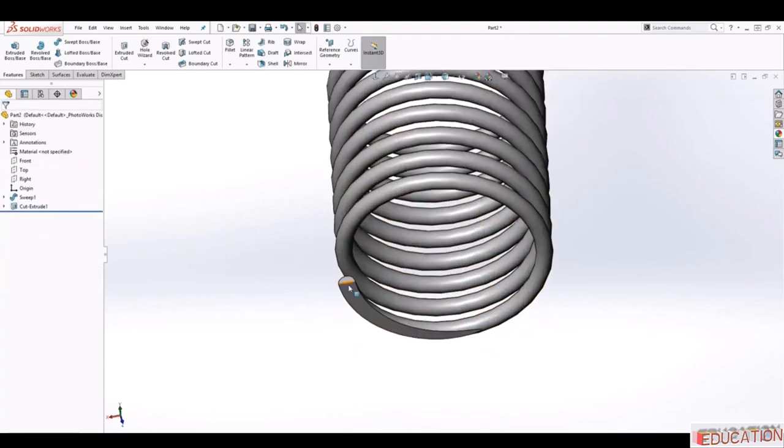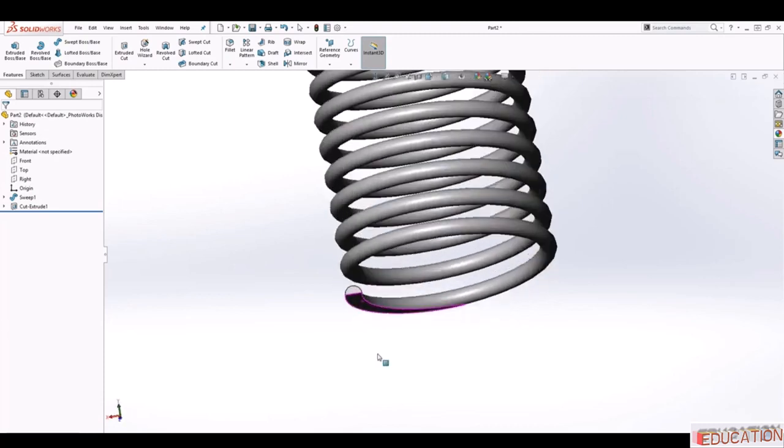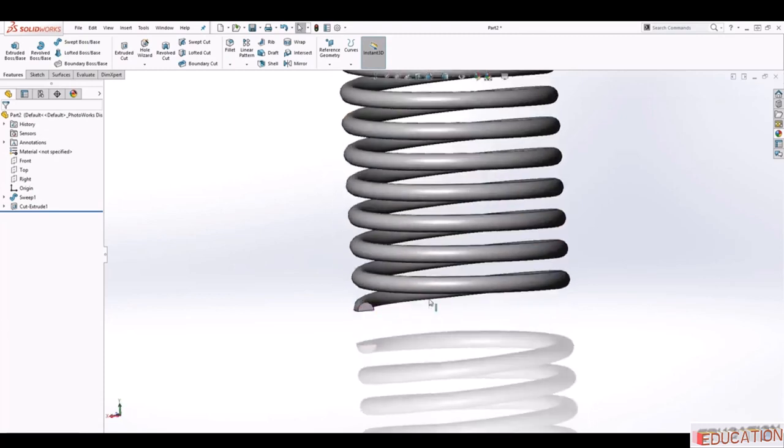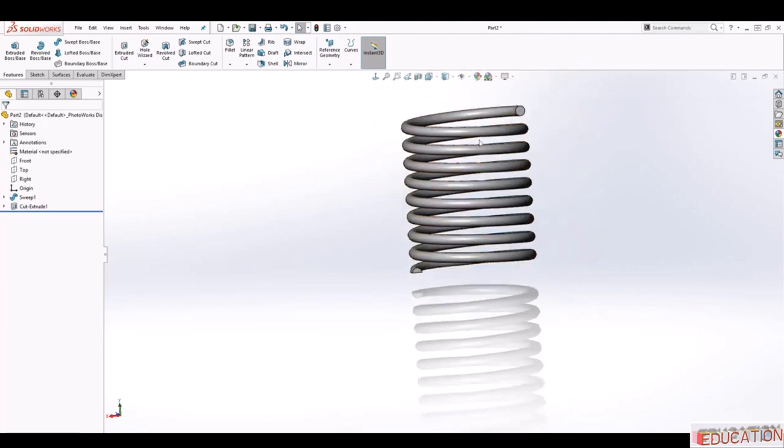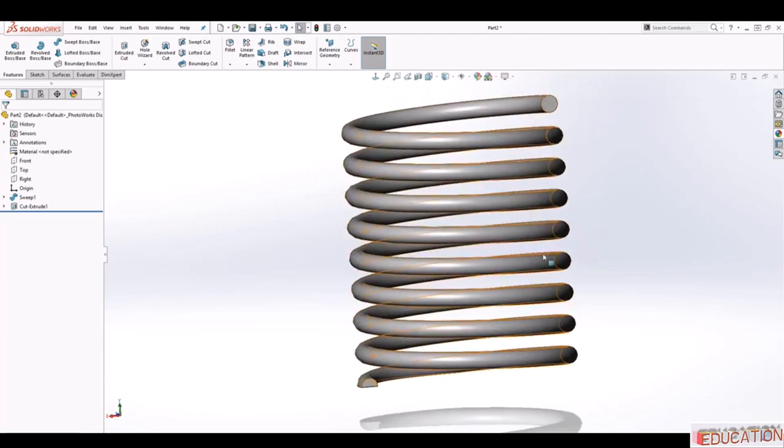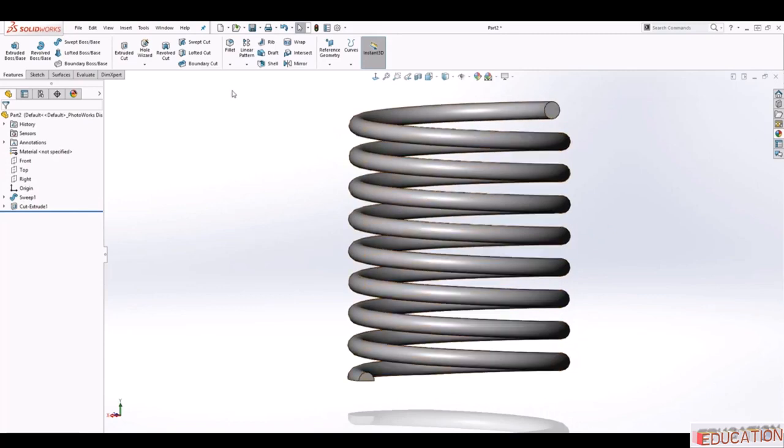So now that is what we did. We just trimmed that flat edge, we trimmed that part off, because when we make it into our part, we want that part to sit on a flat part, and you'll see why we did this later on in the lecture. So the next thing we need to do is just mirror that feature up there to do the same thing for the top.